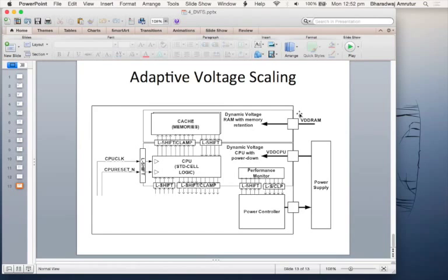So now I'll just introduce this, but we'll go into more detail in the next class. That was dynamic voltage scaling, where the interface issues are: how do you handle the different timing and voltage domains? Whether you do dynamic or adaptive, you still need to do that. Now the thing with DVFS, as I said, is that you have some fixed table which you have to pre-characterize during design time and then use that F2V mapping table. Can we figure out per chip what the actual F2V mapping for that chip is? If you can do that, then per chip you can adjust.